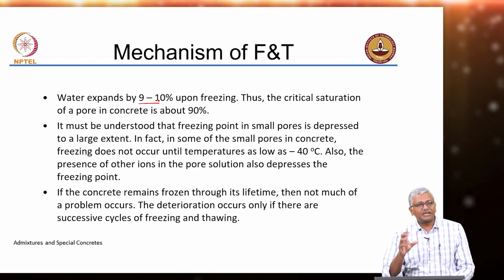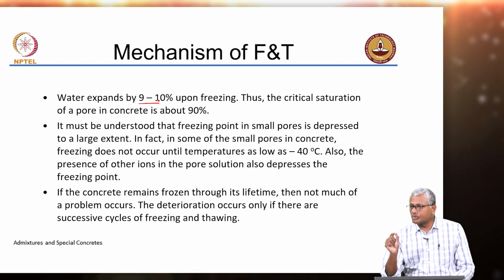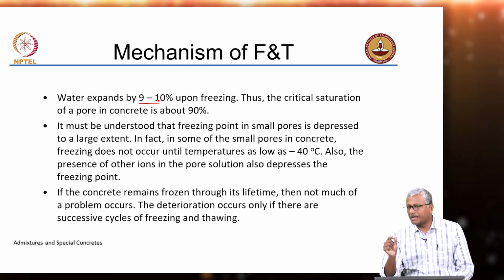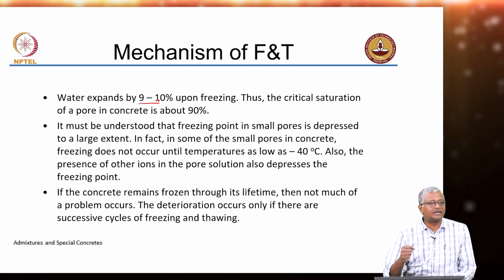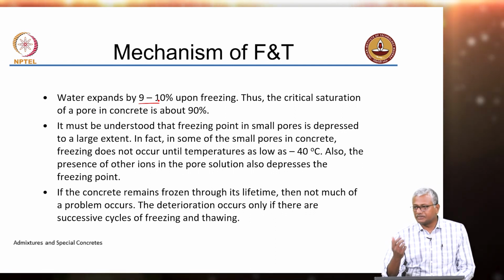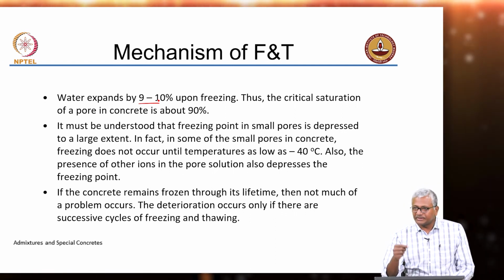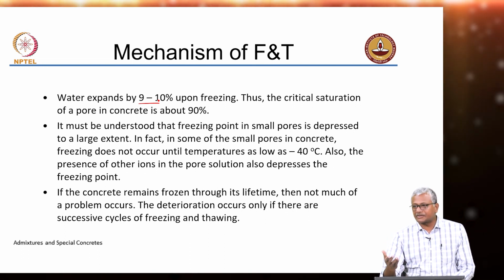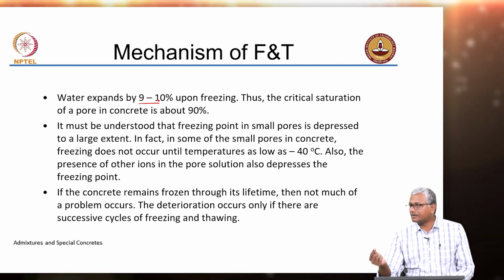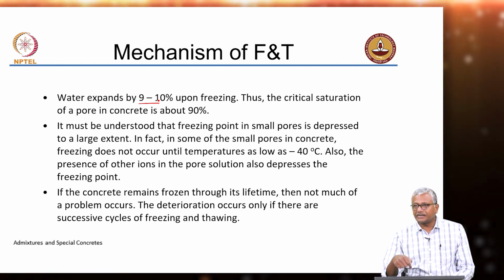But before that, we need to understand that the pores can be very small, and when the size of the pores reduces, the capillary pressures are so high that freezing cannot happen easily. Further, if you remember, when cement reacts with water, there are alkali ions that get dissolved in the water.